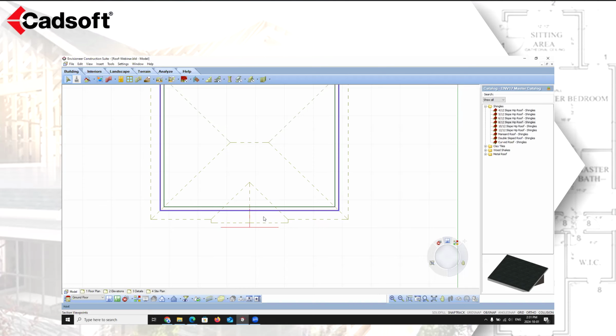While you're doing that, I'm just going to go over a quick review of what we've covered in today's class. There are different ways of inserting a roof in Envisioneer, and the method you choose depends on where the roof will sit in relation to the exterior walls. Roofs can be customized to achieve virtually any style or configuration that is desired. Use the Roof by Perimeter tool to automatically insert a roof over the perimeter walls of a selected building location. The roof is then going to be connected to the walls, so if you change the wall layout, the roofs will also change with it.